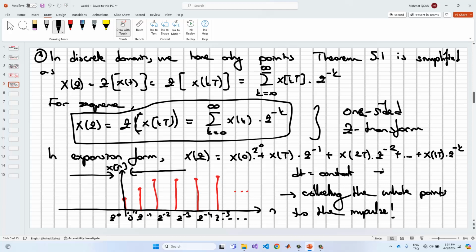Also we can write the algebraic equation. Just remember the Laplace transform, the S domain. For example, H(s) is equal to 5 divided by s plus 5. Okay, and so we can evaluate the signal based on this transfer function, right? And so this transfer function represents the final dynamics of this system. And so this system behaves based on this characteristic, right? We have the time constant, we have the amplitude value in here, okay?